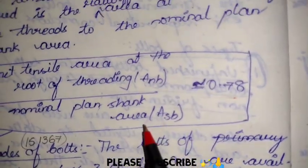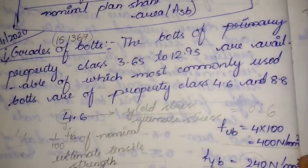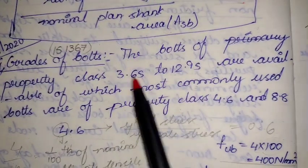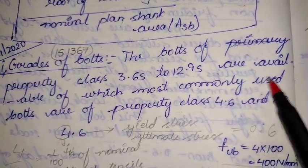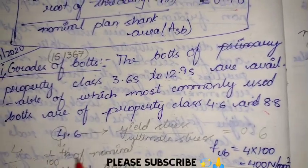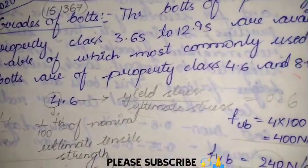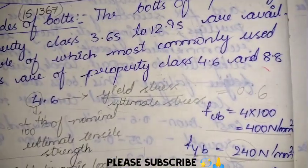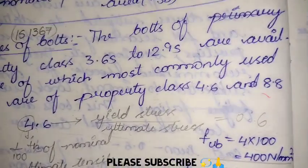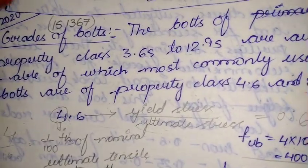Okay, so here we are also specifying the grade of the bolt. What is the grade of bolt? Grade of bolt is nothing but the bolt's property class. The most commonly used bolts are of property class 4.6 and 8.8. So here we are specifying the grade, like in concrete we mention M15, M20. Those are the concrete grades, but in this case we are mentioning the grade of the bolt.